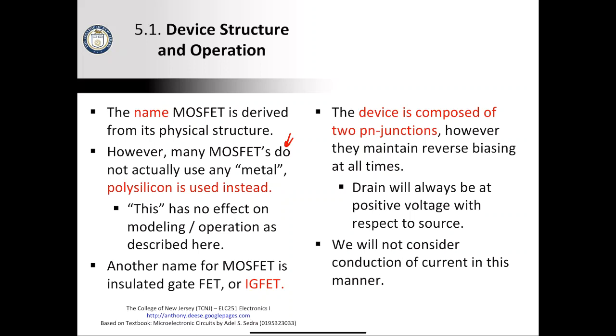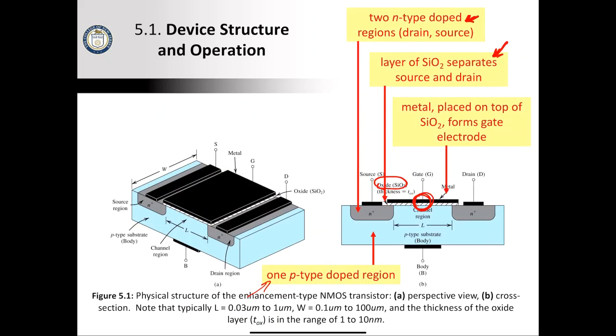So what am I saying right here? If you look at the basic structure of the MOSFET, there really is no distinction between the positive and the negative terminals, or what the expected polarity across the MOSFET is. And so it doesn't matter. You can switch them. They are interchangeable. Normally, we assume that the positive end, we'll call that the drain, and then the negative end, we'll call it the source. And then if you're applying an AC voltage, then those values don't have as much meaning.